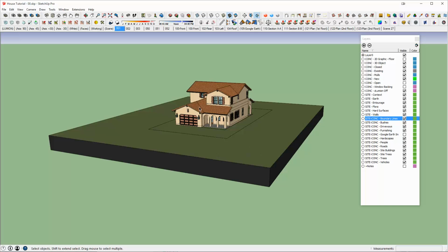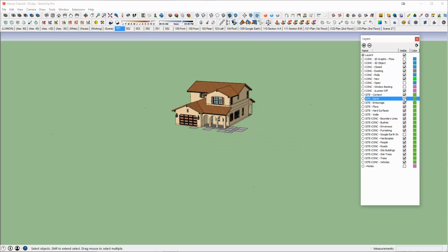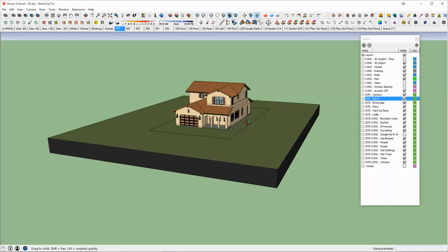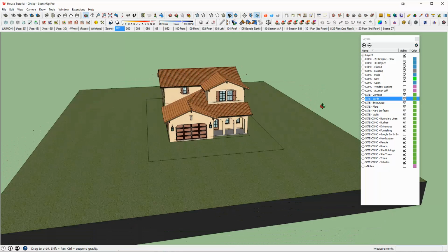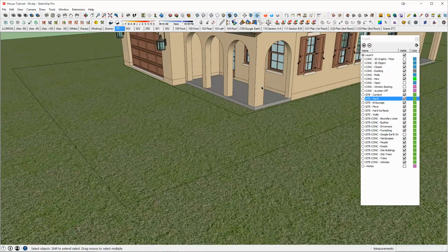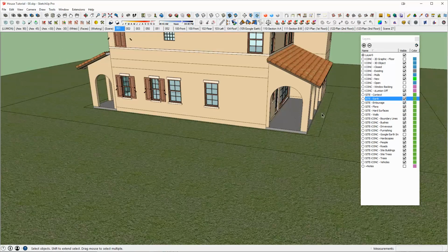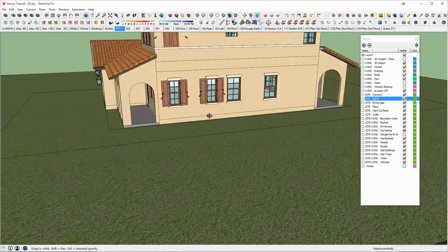And what's nice is putting it inside of my Site Earth box. If I turn Site Earth off, which is right here, everything turns off, including the boundary lines, even though that's not turned off, because it's inside of it, it goes away with it. So now you can see that while building the model, we have some great reference points, to show property lines and setback lines and what have you.